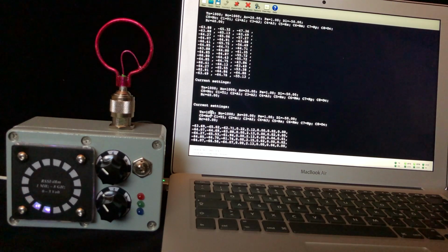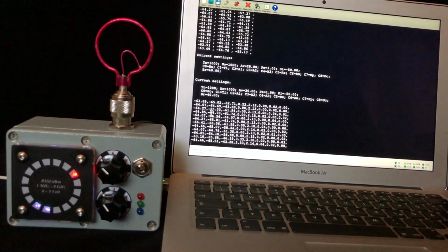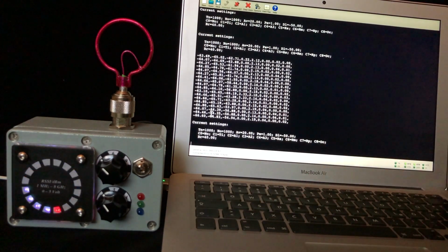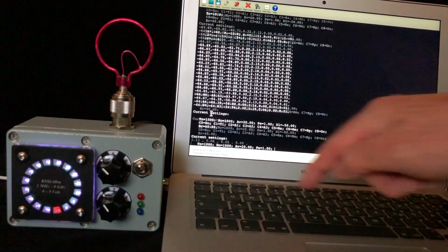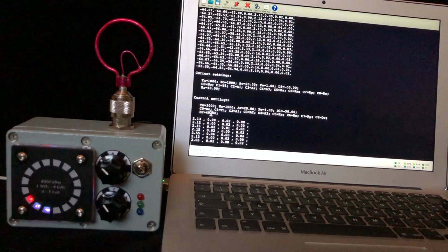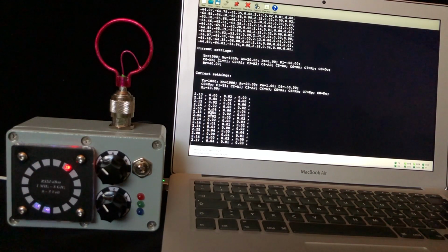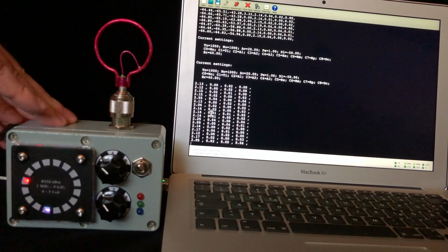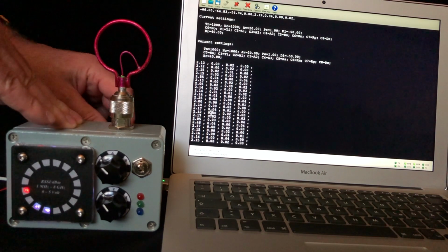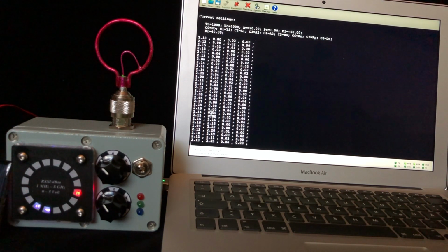Here I have another tip. A nice idea is to feed the comma-separated values directly into a telematics program. I will explain this occasionally in another episode. I need to mention that for the Arduino Nano, your PC needs a USB driver. You can get it either by installing the Arduino IDE, or you can download a separate USB driver you can find on the internet.